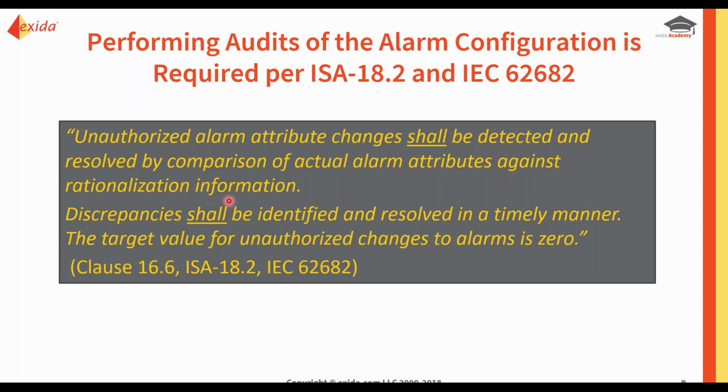So it's expecting you to compare to the design and the results that were established during rationalization. It also says discrepancies shall be identified and resolved in a timely manner. The target value for unauthorized changes to alarms is 0. And I have underlined the word shall, which shows up twice in this reference, because that means these are requirements. This is something that you must do.